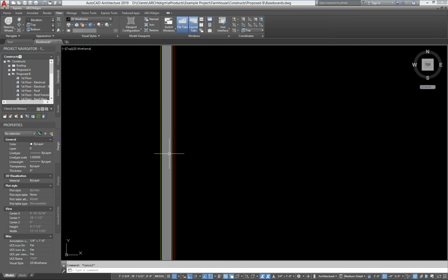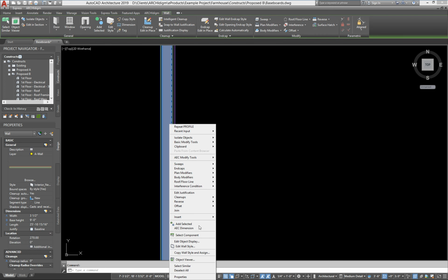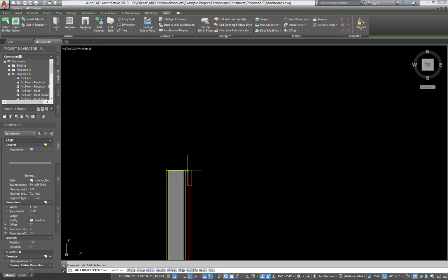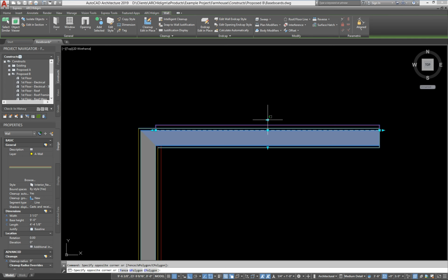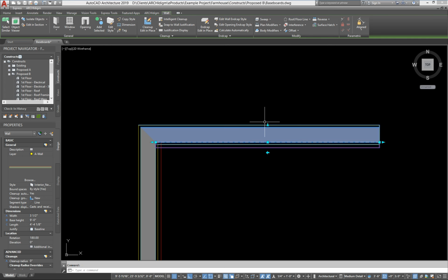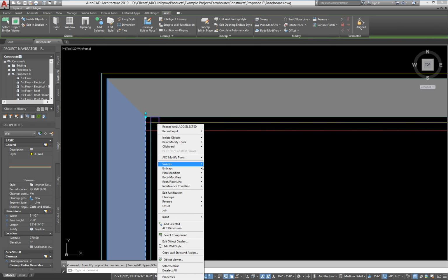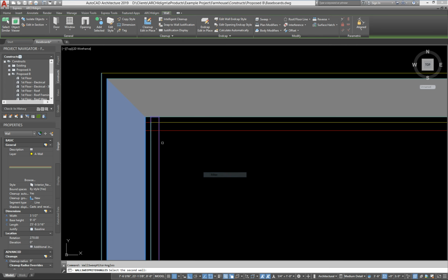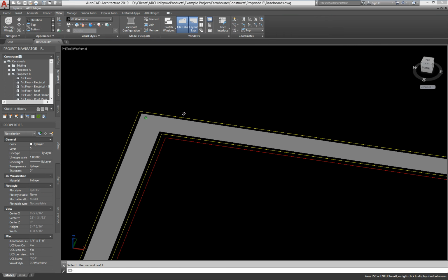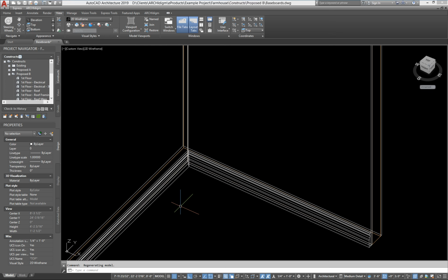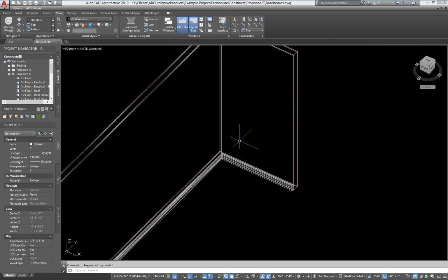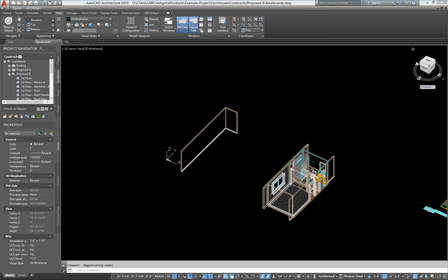If you have two walls that come together, that's selected. Let's say they kind of come across like this. I'll just flip this over. Come on, there we go. You can go ahead and right click, go to sweeps and miter, and pick these two. There you go. So you clean up that corner. Right. So just know both and decide what works better. Just learn the two techniques. I've even tried doing it with a railing, some minor success.